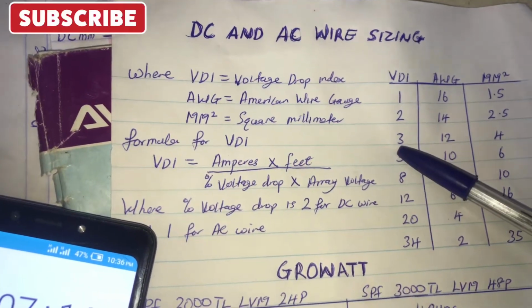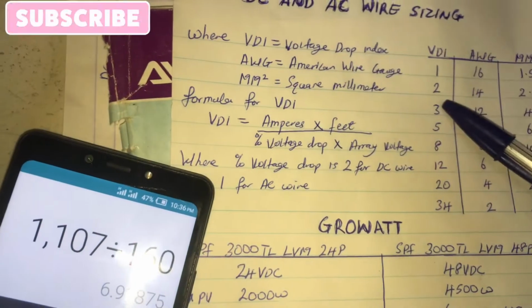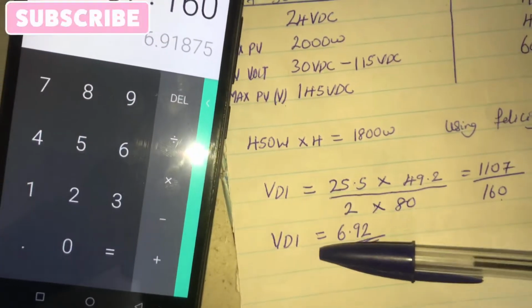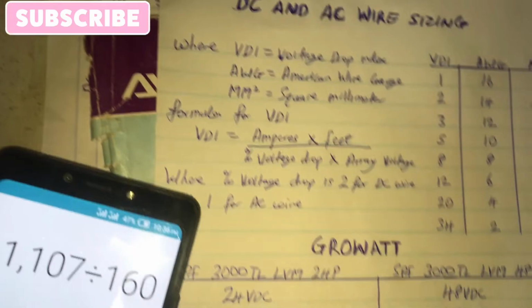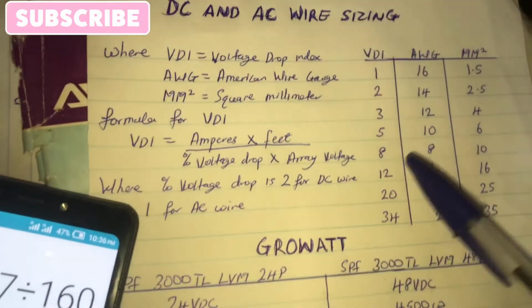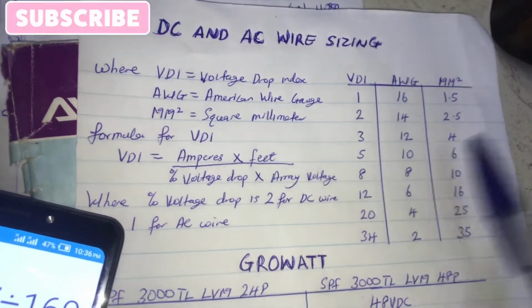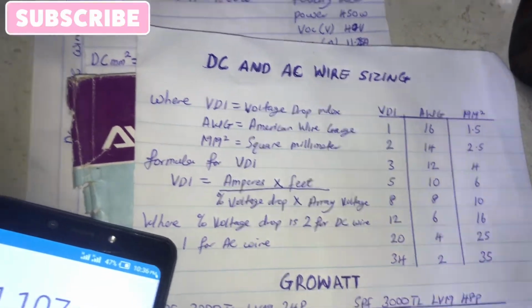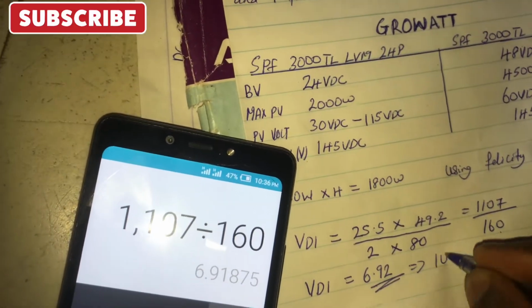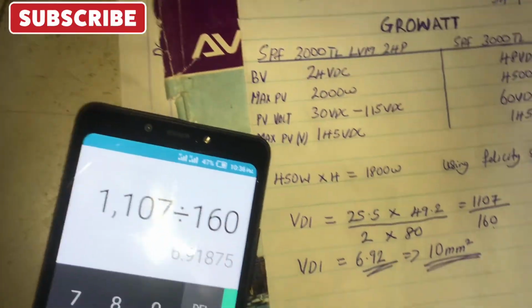3, 5. We did not have 6 and we did not have 7. So once you get any value that is not here, you just round it up to the next one, which is 8. So what we have is 6.92, which is 8 here, because there is no 6, there is no 7. So the nearest number there is 8. So 8 in AWG is still 8, but in millimeter square is 10 mm, as we normally call it. So what you will use for this is 10 mm DC cable.